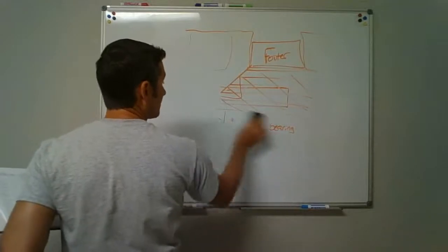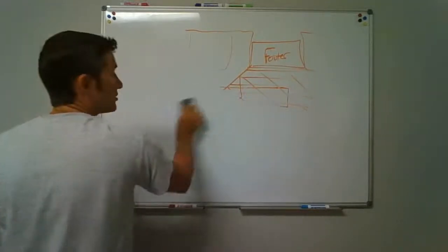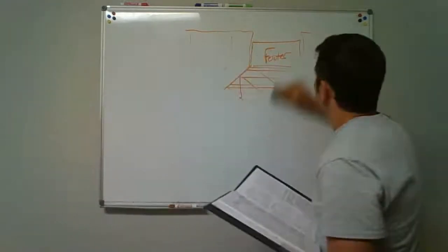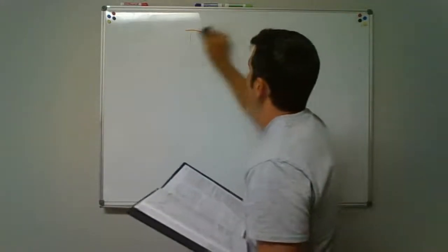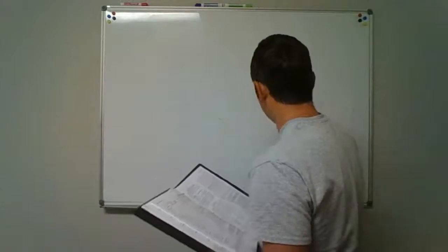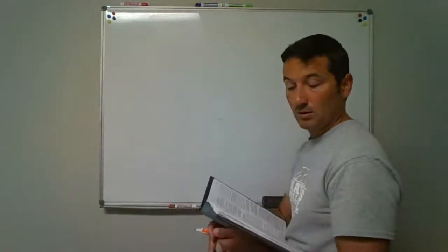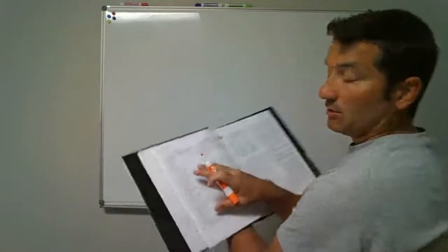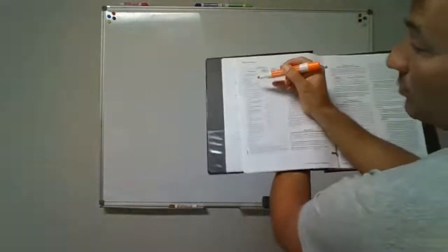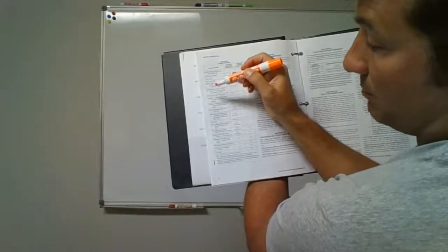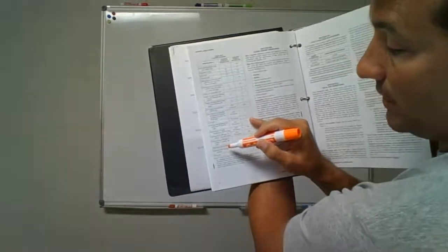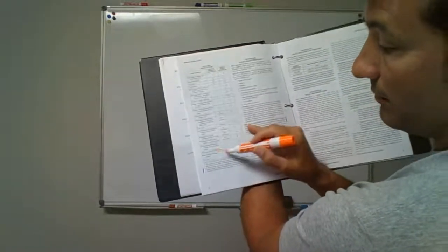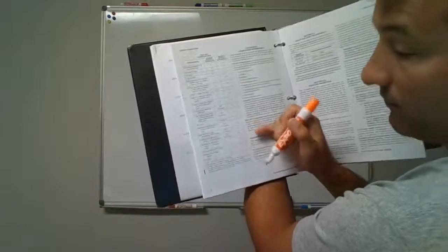I ask you, what's the maximum distance between hangers on the PVC pipe? Now, everything we've been running so far is horizontally run PVC pipe. So you look at your chart, you find the material over on the left side and say, okay, we've been running PVC. So we drop down to PVC, polyvinyl chloride, horizontally run pipe, maximum of 4 feet.